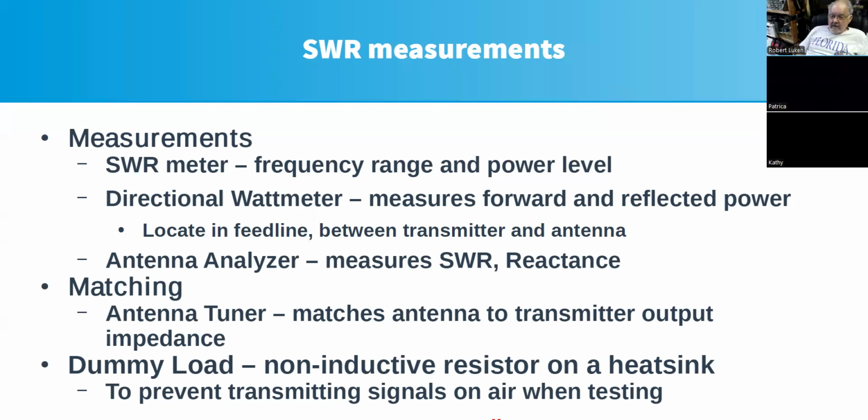So the main thing is the dummy load, which you can use for testing, so you don't have to transmit on the air. You just connect up to your dummy load instead of the antenna. And then you can test your setup and make sure everything seems to be working correctly into the dummy load.